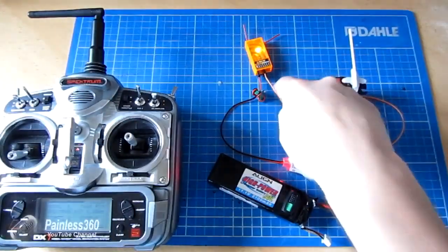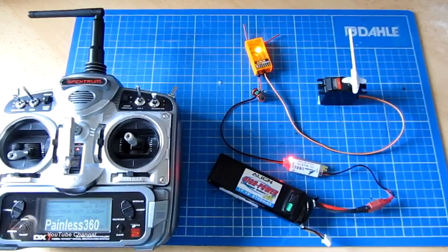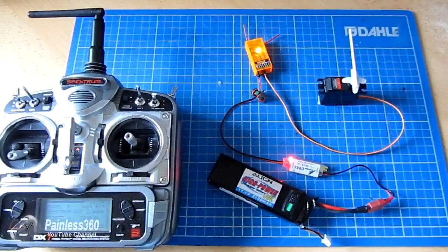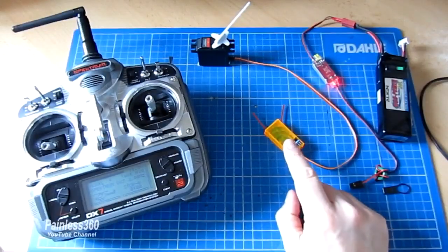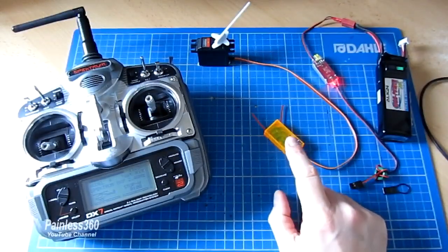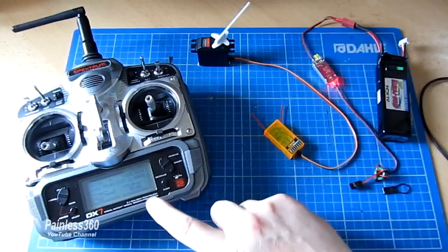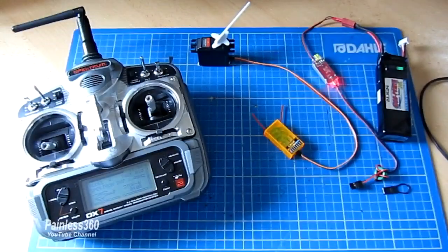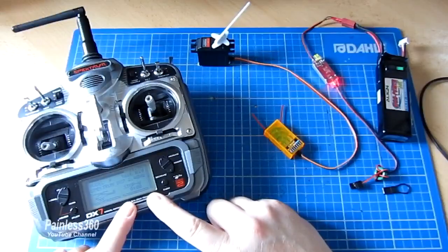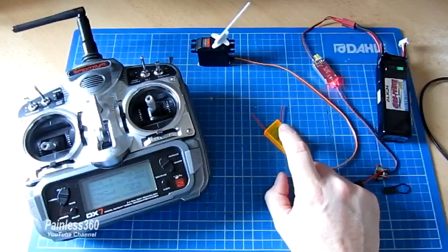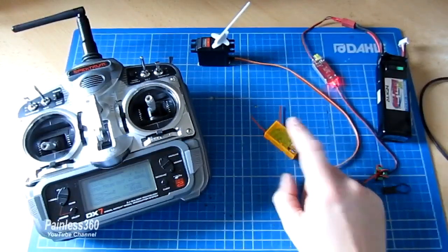Now, we need to talk about how we do the failsafe and also what that means, but first of all, let's go through the process of binding the receiver to the radio. So we'll bind the radio to this receiver again, and not only are we binding the radio and the receiver, we're also binding the receiver to this radio with this specific model memory. Now, that's important, and it's a fail-safe feature, so that if you have a different model selected to the one that was selected when the bind happened, this receiver will not power on and activate.